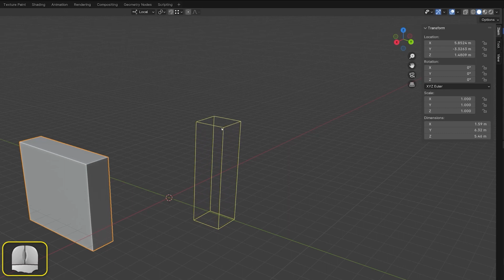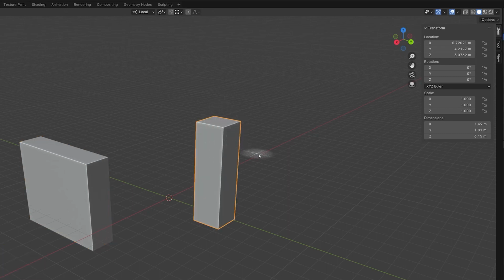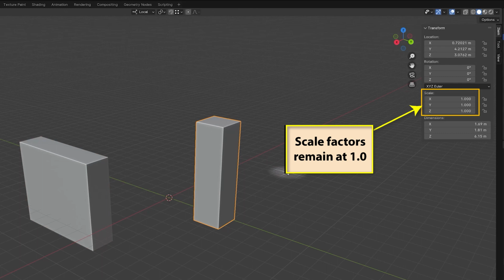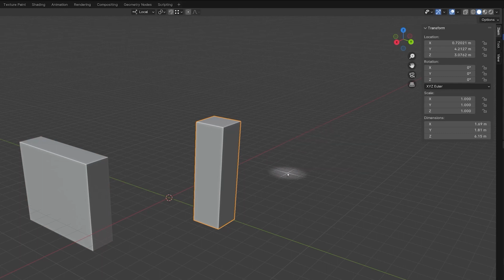Notice, however, that if the box size was set solely while dragging out its dimensions before it switched from wireframe to solid mode, the scale factors do not change from their initial 1.00 value. As we move the mouse around the 3D viewport, we can see that the grid realigns itself to lie flat on any face that it moves over.